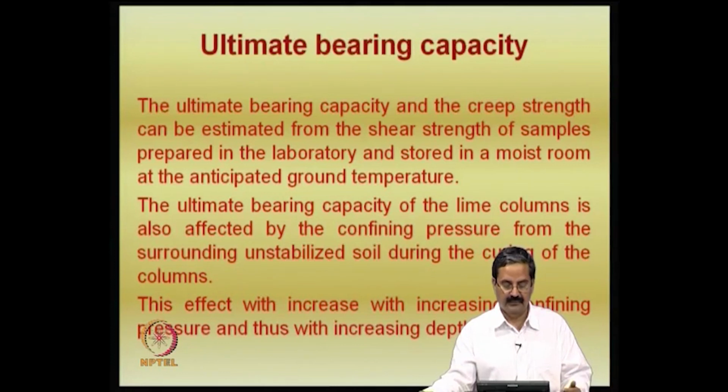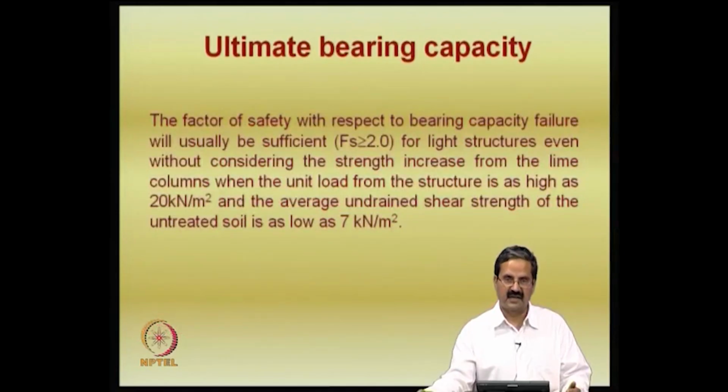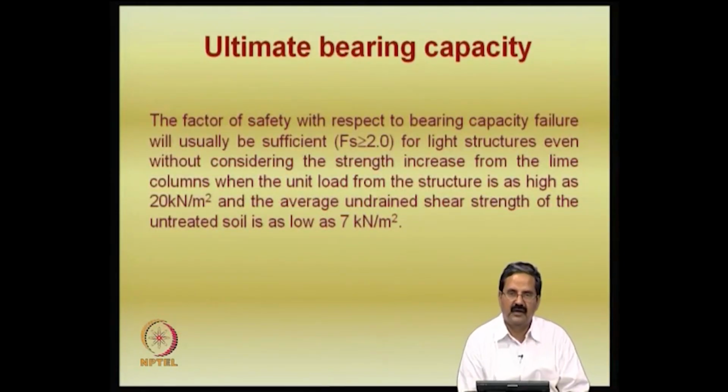And how do you get the ultimate bearing capacity? The ultimate bearing capacity is obtained from the strength of the samples. The unconfined compression test is one simple test one can do, and as I just said, the confining effects are there, particularly when you are trying to use this.